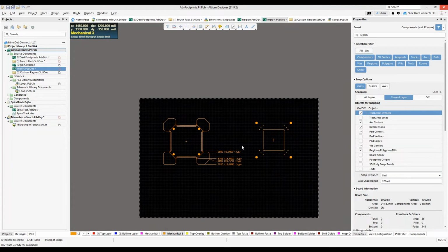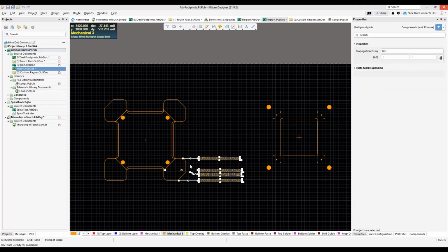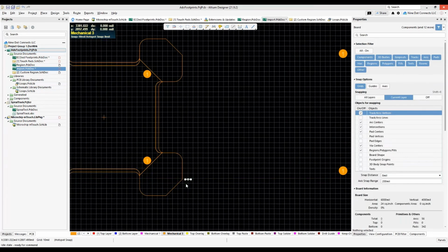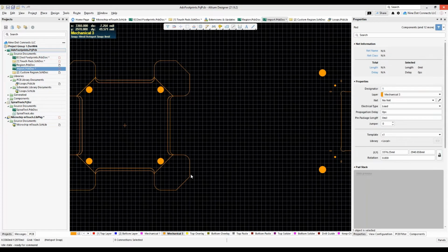Okay. Now, what if you can't get it in? It's like you've tried it, you're trying to figure out what it is. It's not the size that you want. What can we do? Well, let's do the following here. I'm going to take all this here. I'm going to do a sweep. The sweep I did is from right to left. So as long as something of that primitive is within that box, it's selected. I'm going to just delete these things here, and then we'll combine this one together, and then we will take a look at how we can rescale this.